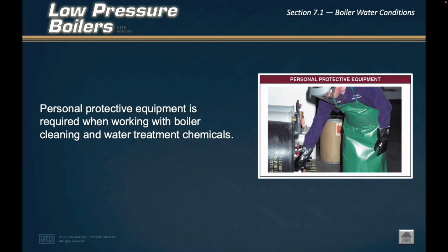Other specific water treatment procedures may be required after certain boiler maintenance. A water treatment program is developed to reduce the possibility of scale, corrosion, caustic embrittlement, priming, carryover, and foaming.